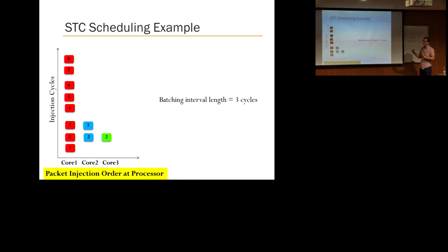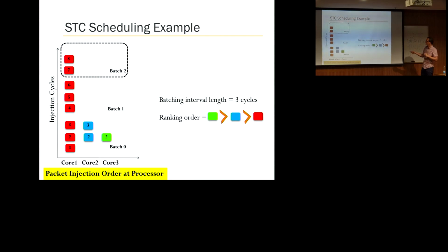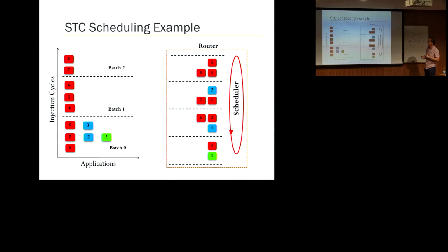And we're going to have a batching policy over here. I'm not going to talk about that, but basically, you're going to timestamp things based on batches. This is your batch, and this is your other batch, and this is your other batch. And we're going to rank these applications again. So it's going to be very similar to memory scheduling. It's principles of batch scheduling without the parallelism awareness really applied to a router. Basically, we're ranking some applications higher than others. Why? Because this application has the possibility to make the fastest progress in its core. It's not injecting as much. This application is injecting a little bit more. This application is injecting a lot. So it makes sense based on what we've discussed so far to rank this one higher, because if you service this, the core is going to make progress very quickly. So that's our ranking order. You somehow compute a ranking, and the router does that ranking and obeys that ranking in its scheduling.